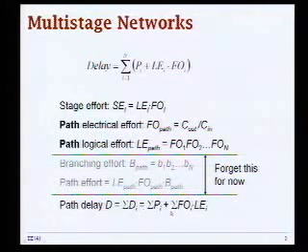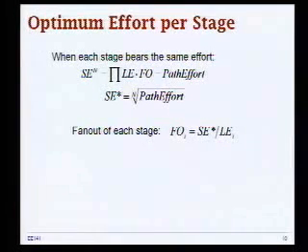And then you can simply express the delay as the sum of all these stage delays. And now you know that the product of this fan out and logical effort, we now call that stage effort. We had basically just the fan out in the previous case when you had an inverter chain, but now we have to include this logical effort of a gate just to see how good that gate is at driving the load.